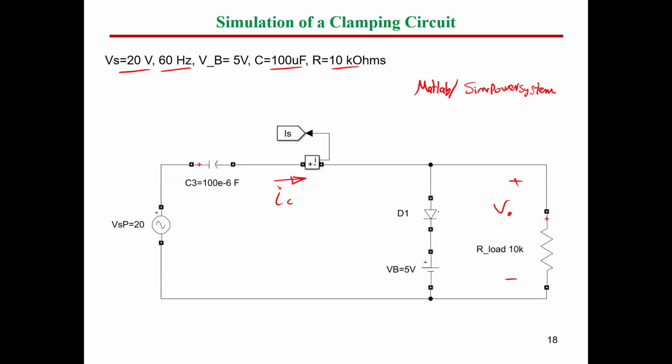Again, the capacitor here will charge with the peak value, which is going to be 20. And the battery volt equals 5 volt. So the expected output volt during turn on of this diode is going to be V gamma, which is the volt across this diode, plus the battery volt, so 5 plus V gamma. And when this diode is open circuit, we expect to have V supply minus V capacitor, which is going to make a level shift for our waveform.